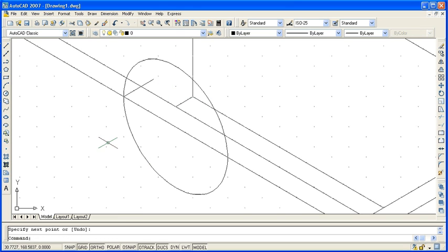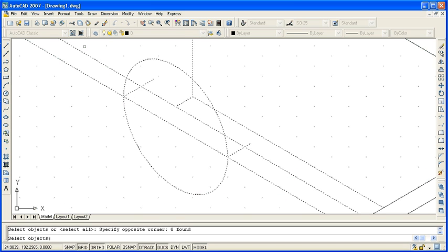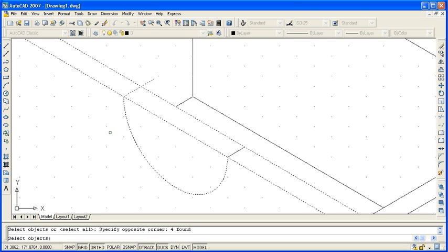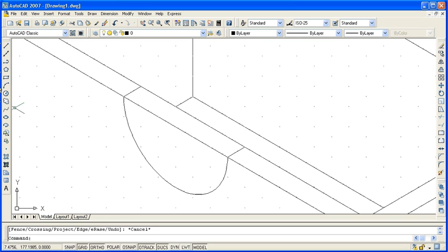use F5, draw a line, enter, again enter, intersection point, INT, select this point, draw a line, enter, then trim, select all, right click, this portion, remove. So now you have to again trim, again complete this portion.